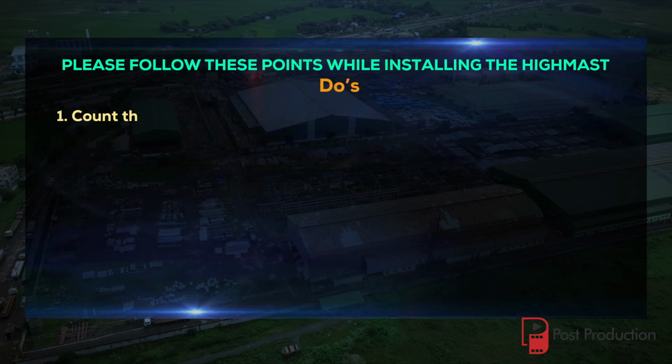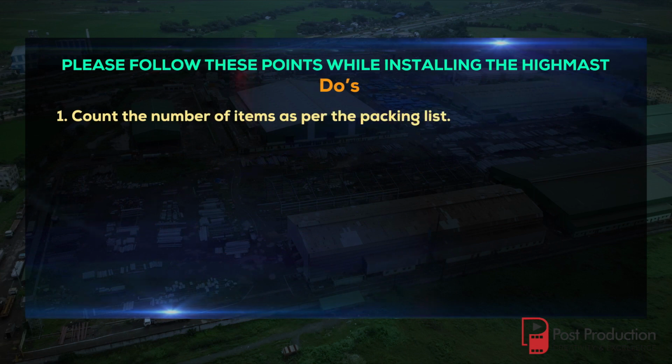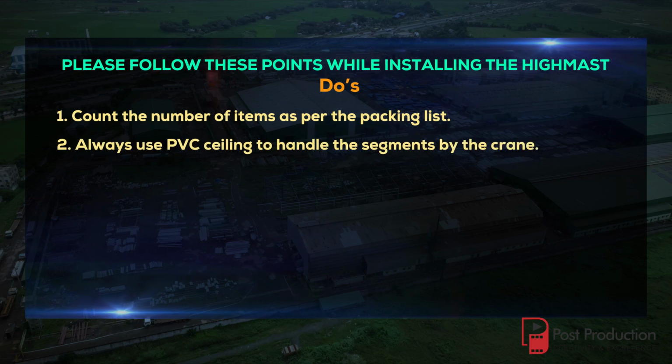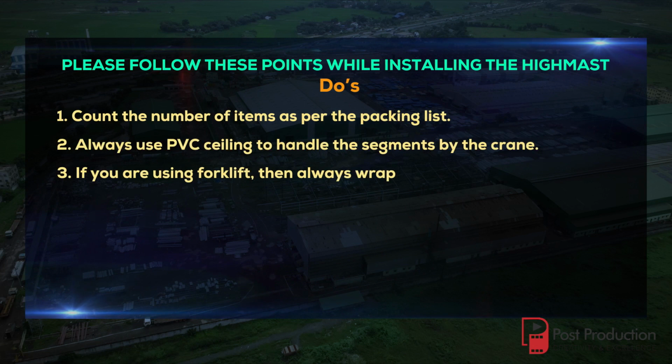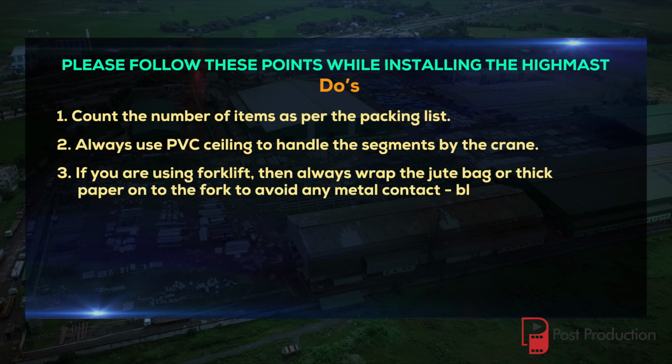Do's: count the number of items as per the packing list. Always use PVC sealing to handle the segments by the crane. If you're using the forklift, then always wrap the jute bag or thick paper onto the fork to avoid any metal contact, black and GI.